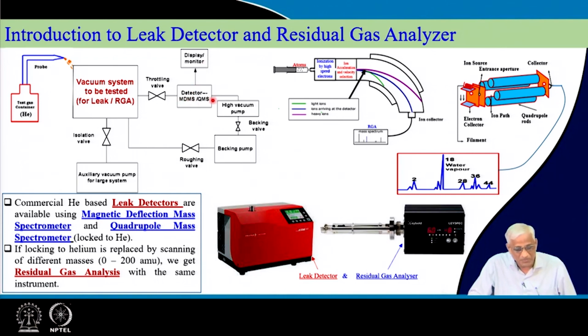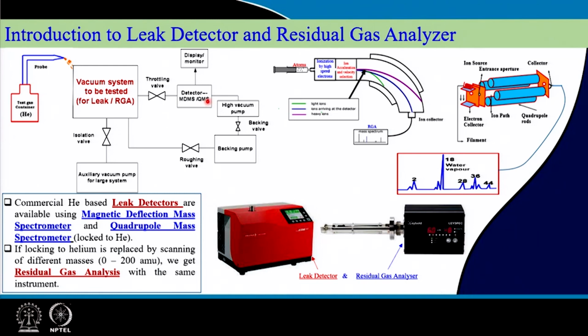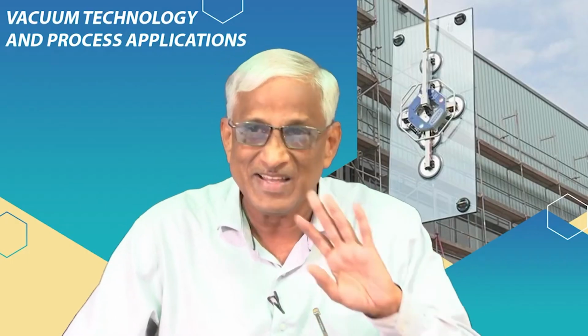Okay. Now, this is connected to a high vacuum pump. Why? These detectors need vacuum for their operation. They are used to troubleshoot a vacuum system, but they themselves require vacuum. It is like cryogenic engineering. Cryogenic engineering requires vacuum, otherwise you will not get low temperatures, but cryogenic engineering can produce the best vacuum in the world. So, like that, in nature you will get such coincidences.